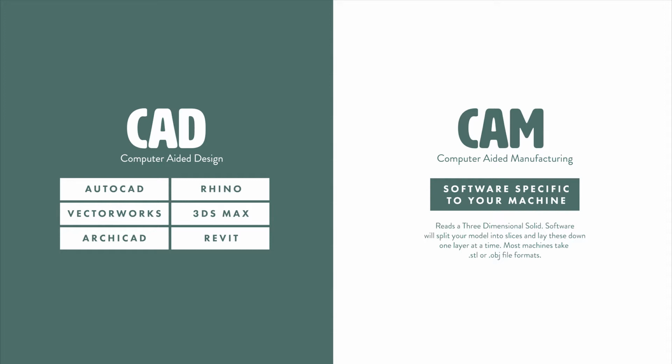CAM is the software that speaks the language of your fabrication tool. So for example, when we're talking to a 3D printer, the 3D printer doesn't understand your Rhino model. What it understands is how far to move in the X, Y, and Z direction, how much material to lay down in terms of its thickness, and how fast to do so. And so what we need to do is convert our drawing or model into that language that our machine will understand.